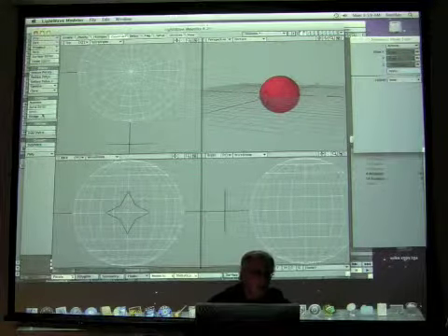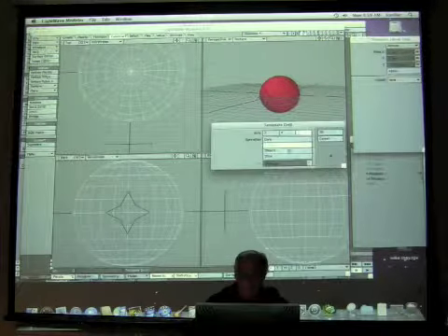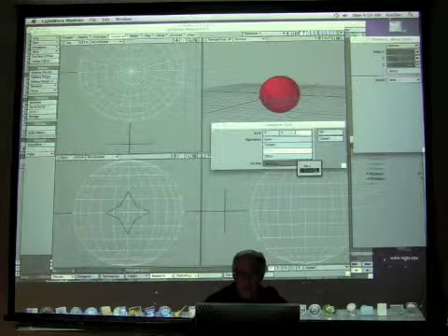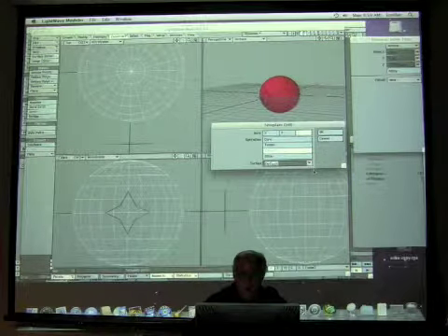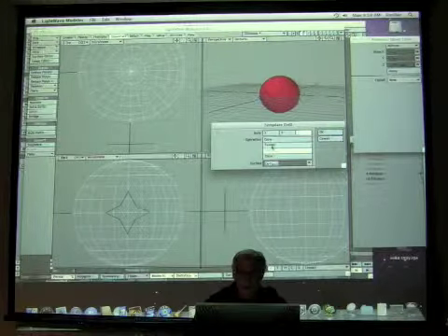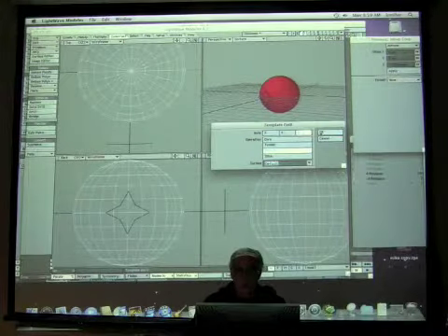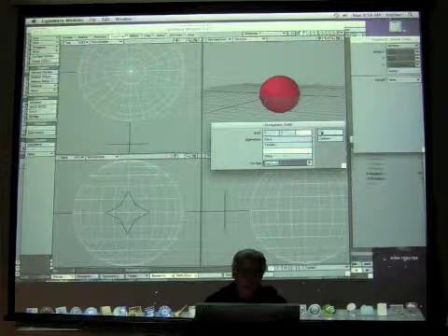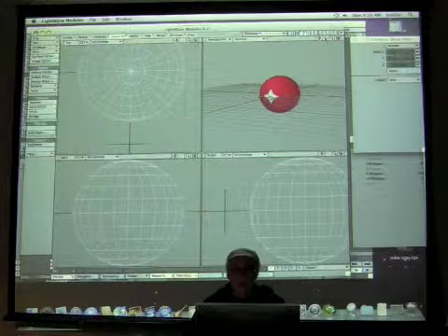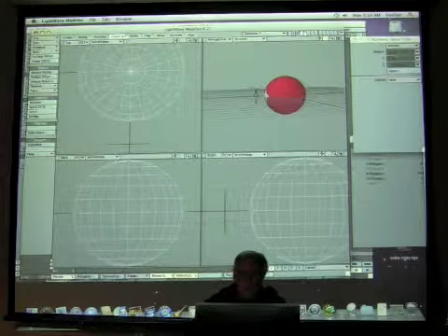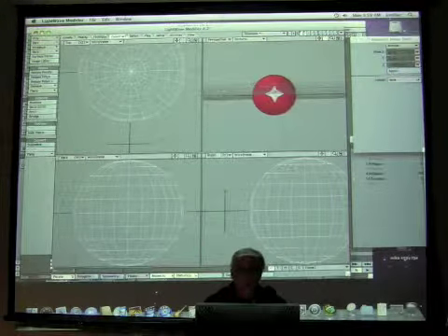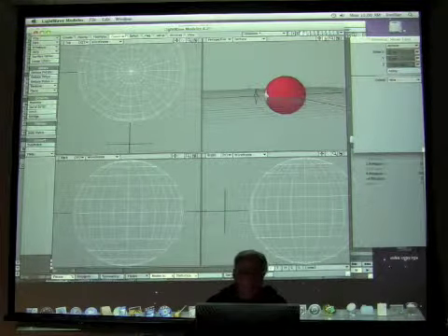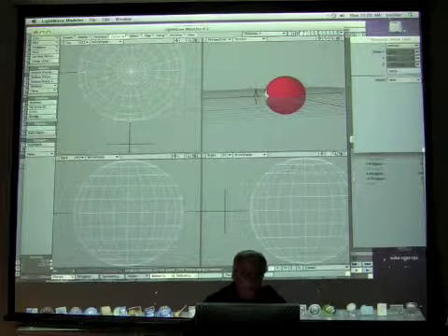So now I'll select construct again. We're going to use drill. And this time I'll select stencil. And also surface, I'm just going to use the default surface for the slice that goes through. Now if I had other surfaces, I could choose from them as well. Click OK and notice what it did. Look at the geometry in wireframe and notice it projected all the way through. And this is now cut through, and you can select these polygons in here.